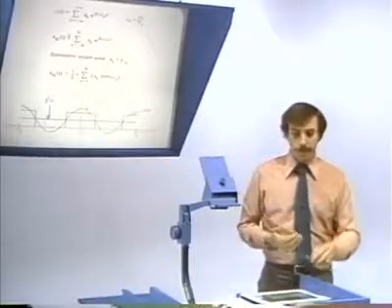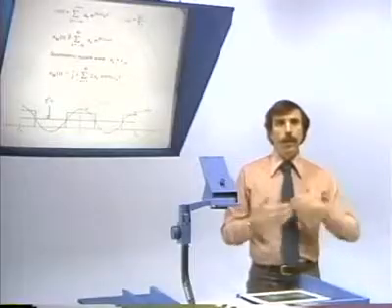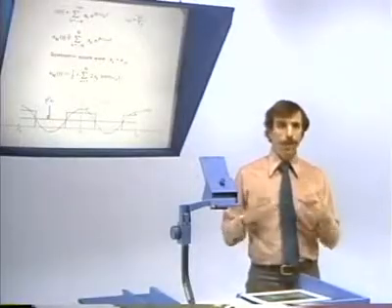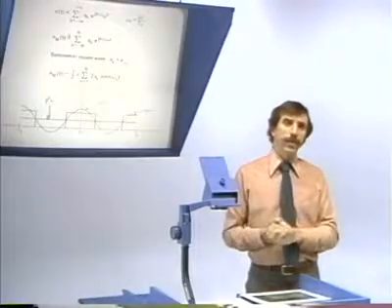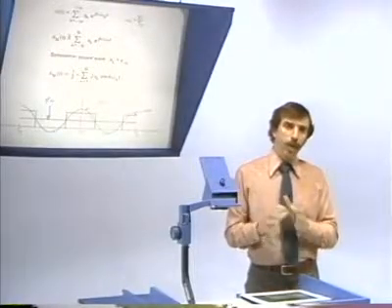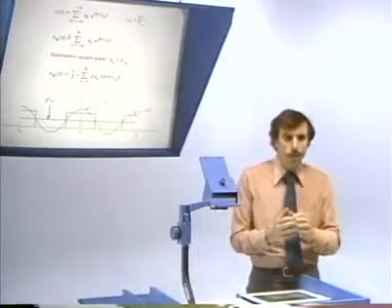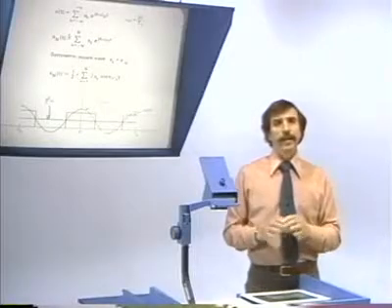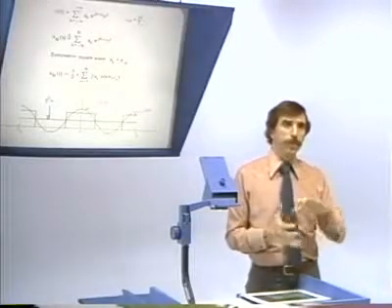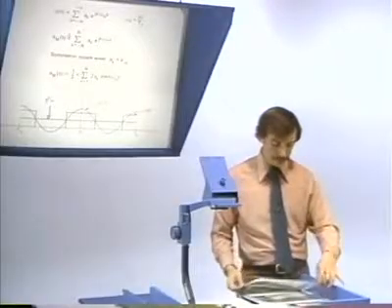And in fact, something that will stand out more and more as we go through our discussion of Fourier series and Fourier transforms is that general statement that it's the low frequency terms that represent the broad time behavior, and it's the high frequency terms that are used to build up the sharp transitions in the time domain.